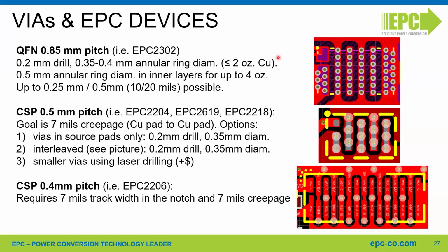So you can have a reduction of the temperature increase on the device by a factor of 2 if you are using PCB only cooling and vias in pad.